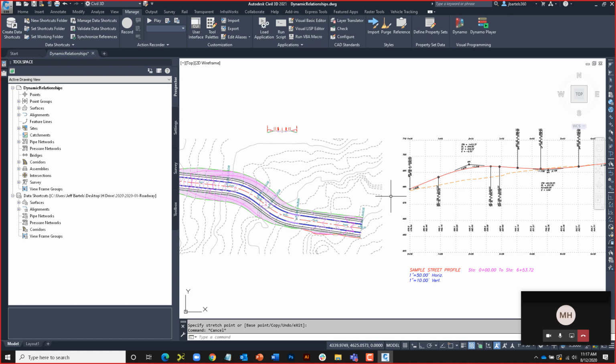Just from a high level, the way this works, you have a Civil 3D project, and in that project, you create these pointers, just like we saw on the desktop, that tell the project, hey, if you want the surface, it lives in this drawing, in this particular directory. And if you want a centerline alignment, that alignment lives in this drawing and has the path to that particular directory where that drawing is stored. Let's take a look at that. We're going to talk about the concept of a Civil 3D project first here.